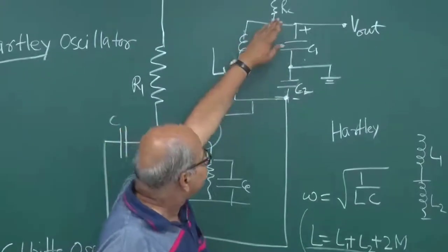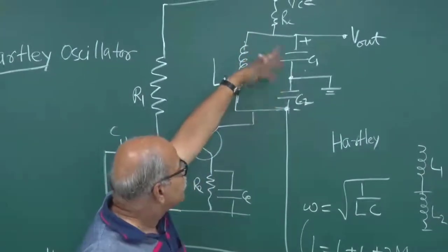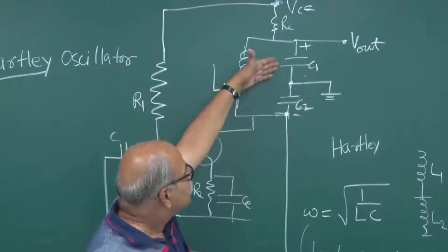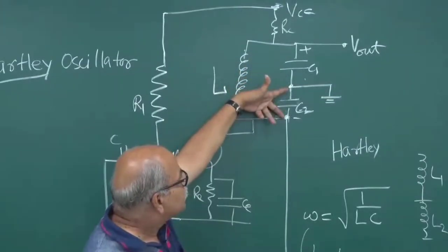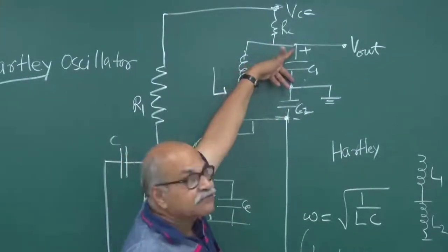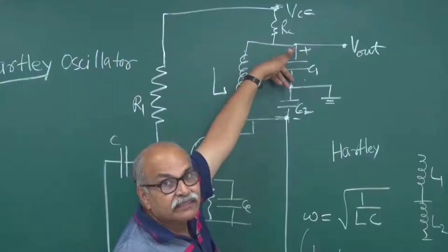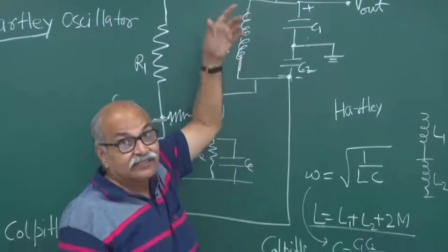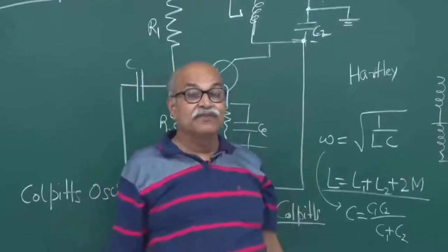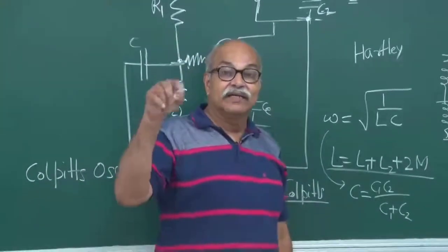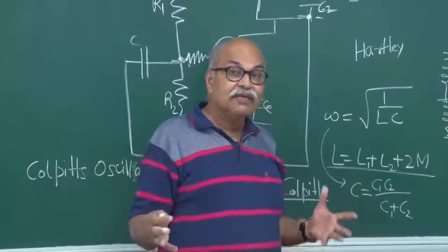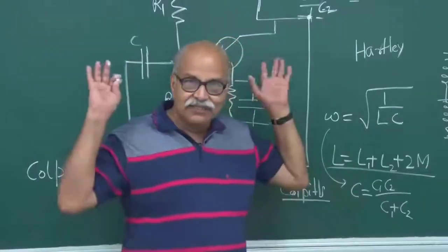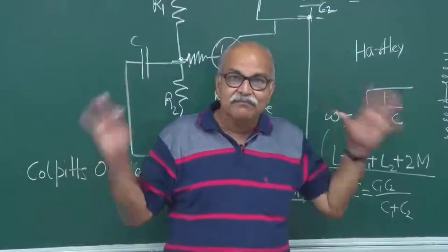Once again they are series connections, so depending on what the reactances are, that fraction of voltage will be here and that fraction of voltage will be there. These are all AC things that we are talking about. So when you use 1 over C omega, L omega, those things will be operative. So this is how the oscillators are generally made.